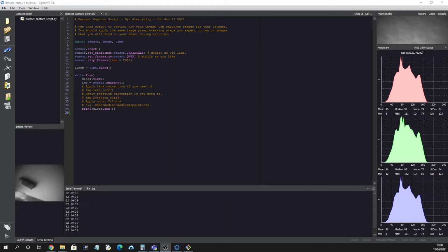To do this, what we're going to do is use this software here called OpenMV, and this is going to help us capture the images, and then it will upload it to a service called Edge Impulse, and then within Edge Impulse that's going to give us an AI model at the end of it. Once it gives us an AI model, we'll open up and copy that across to the Arduino Portenta. So first of all, we need to actually connect to the Portenta.